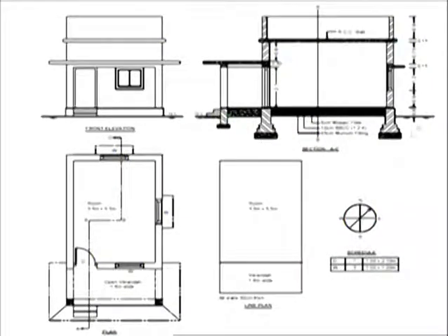So there is no need to have another section, either horizontal or vertical, correct? Either in this direction or in this direction, this is not required. Only this single sectional elevation is sufficient to give us all the vertical dimensions. So this vertical section gives us dimensions of all these details. You see the foundation concrete, how deep we have to do the excavation, what is the thickness of the concrete, then what is the thickness of each and every layer,